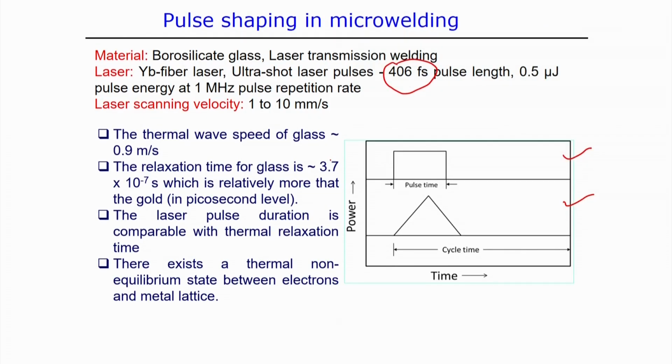When the relaxation time is more as compared to the pulse duration, it is a better option to analyze this phenomenon using the non-Fourier effect of the heat transfer mechanism. This mechanism is based on the existence of a non-equilibrium state with the application of the femtosecond level pulse on the substrate material.